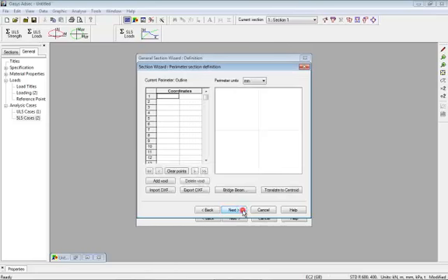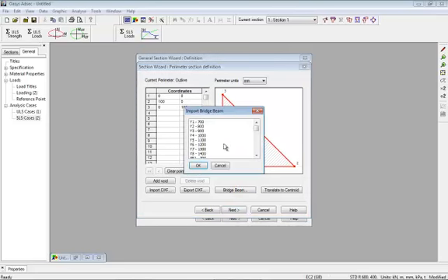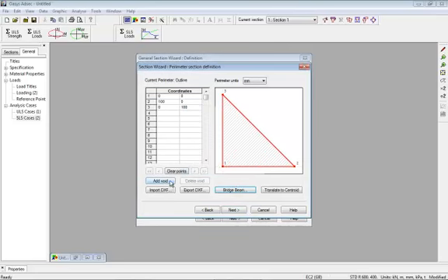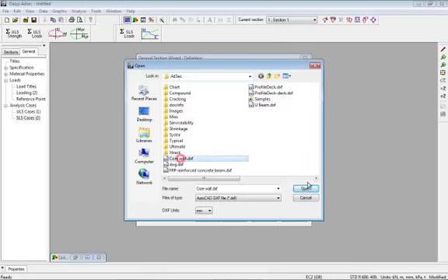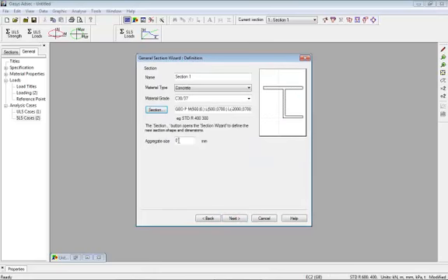Now, perimeter section, you actually define the corner coordinates of the section, and you can type them in, and define the section this way. We do have bridge beams which you can add in, but I happen to have drawn a core wall in AutoCAD first, or CAD, and so I'll just go and choose that core wall, and see it imports this DXF, which needs to be a closed polyline, and you can see there are the coordinates of the wall.